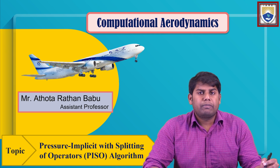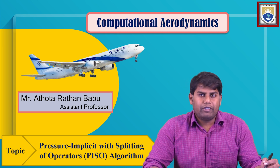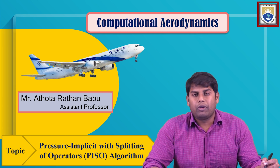In today's lecture, we will see the PISO algorithm, which is pressure implicit with splitting of operators. This PISO algorithm is used for unsteady simulations or the transient simulations of CFD. And in the previous session, we have seen the SIMPLE algorithm, where these algorithms are used for steady state simulations.